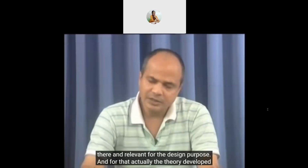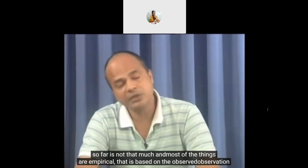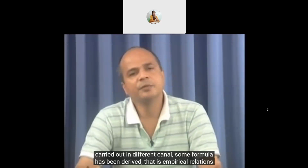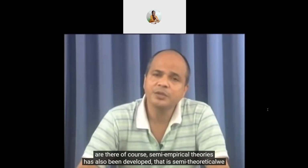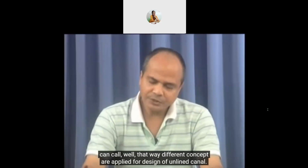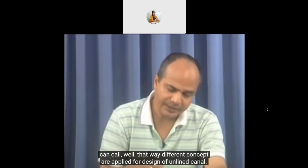And for that, the theory developed so far is not that much, and most of the things are empirical, that is, based on observations carried out in different canals. Some formulas have been derived, that is, empirical relations are there. Of course, semi-empirical theories have also been developed, which we can call semi-theoretical. That way, different concepts are applied for the design of unlined canals.